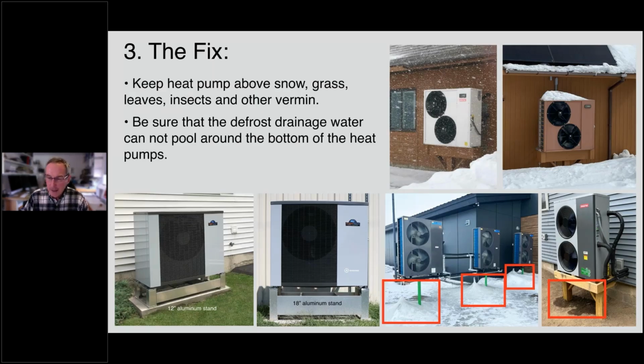And this photo that has the 3 red rectangles in it, this is up in northern Canada. And what I want you to see in these rectangles are these, I'll call stalagmites made out of ice. That is not water that was leaking from the heat pump. It's water that would drain out during defrost. Now imagine those heat pumps were just 2 or 3 inches up above grade on a concrete pad.